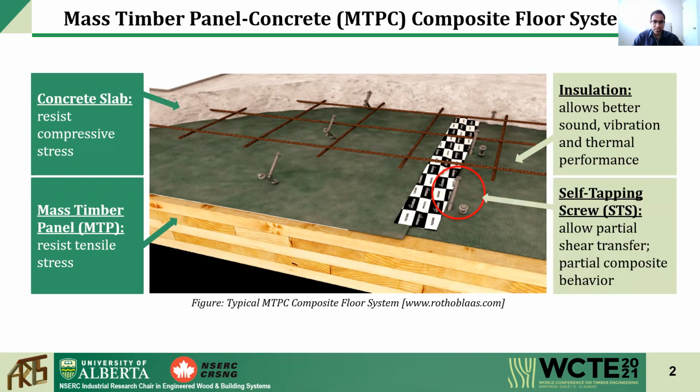The shear connector, in this case an inclined self-tapping screw, which penetrates all three layers of concrete, insulation, and timber, allows for partial shear transfer and therefore partial composite behavior. The structural efficiency of this composite system mostly depends on the performance of the interlayer shear connectors.